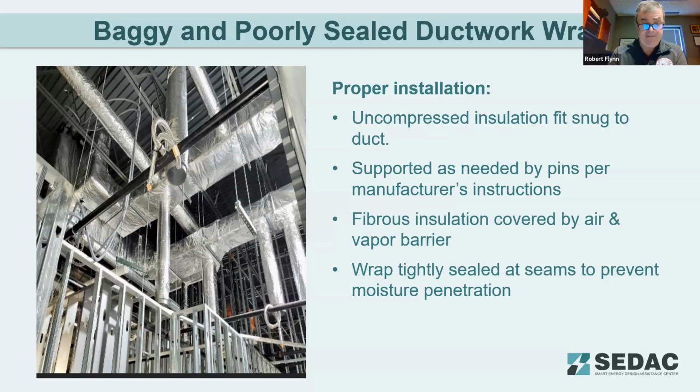Myself, I'm not a tinner or a sheet metal worker, but from what I've seen in the past, the system itself should be sealed, so outside air doesn't come into the system. Even if you have insulation around that duct system, it should be 100% sealed with some kind of sealer, like a gray sealer that they put around the seams of each one of the duct pieces of ductwork.